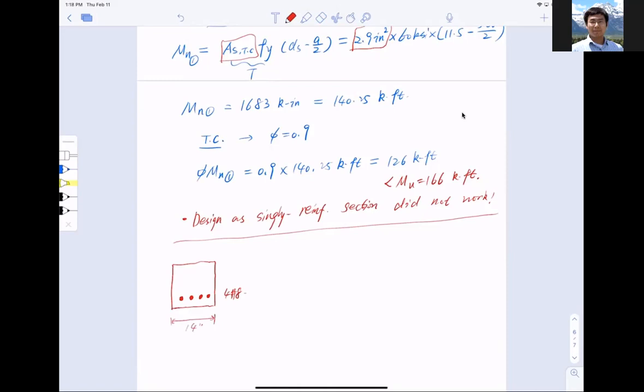And even if you fit them in, you say, you know what, I'm going to increase the steel, right? So you put another layer of steel, for example, to increase the tensile reinforcement area and gain more moment capacity. What happens is, yes, indeed, you increase AS, and you increased the T, which is AS Fy, okay?